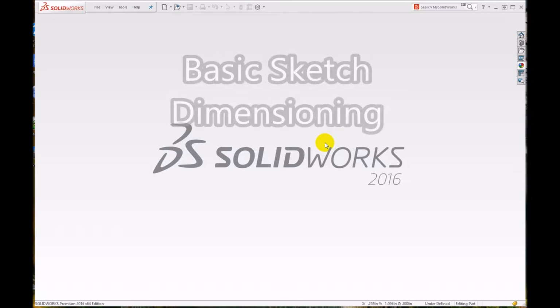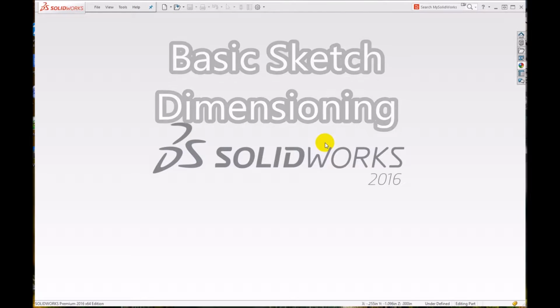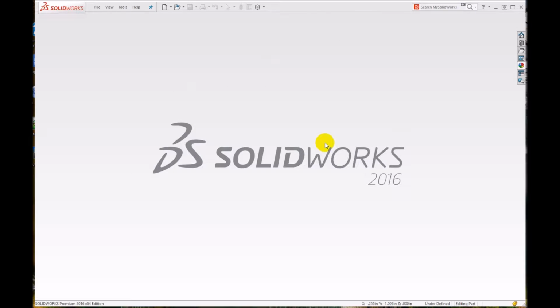Within SOLIDWORKS, when you're defining a 3D model, you'll initially create a sketch and then refer to that sketch when creating a feature, one or more features. Within those sketches, you need to define how big things are and where they are located in reference to each other or to your datum. We'll describe datums later on.